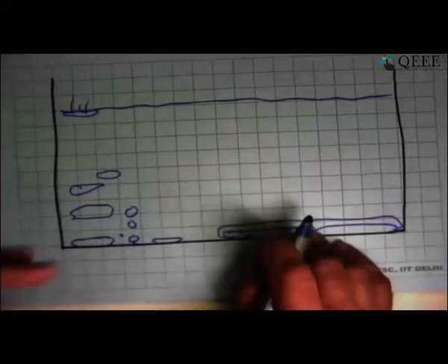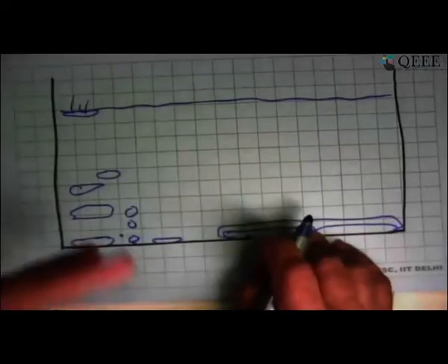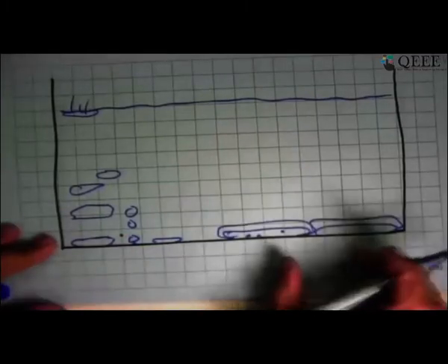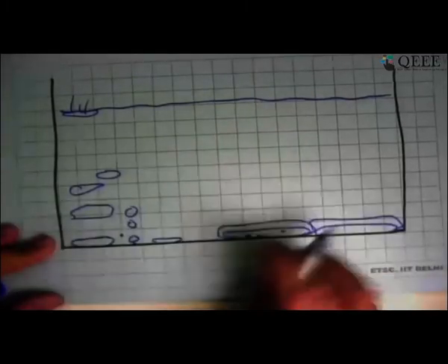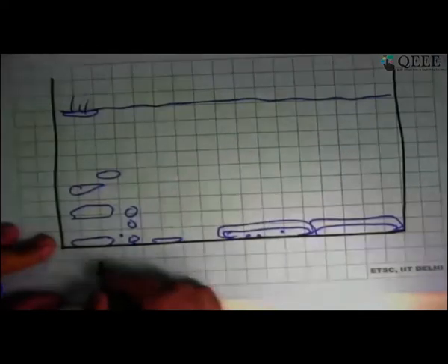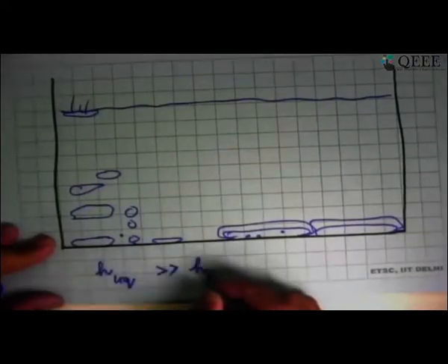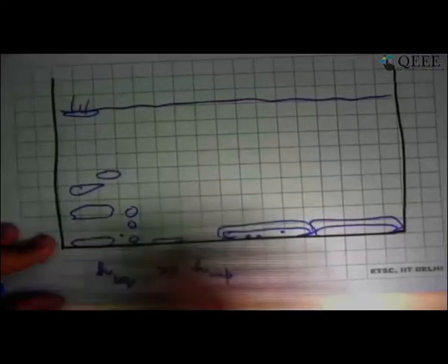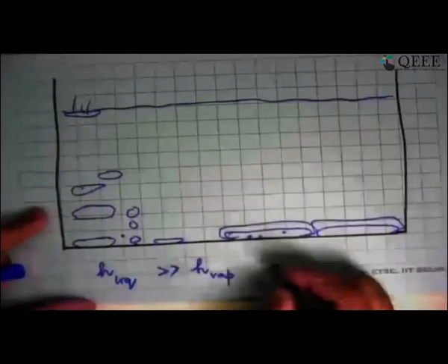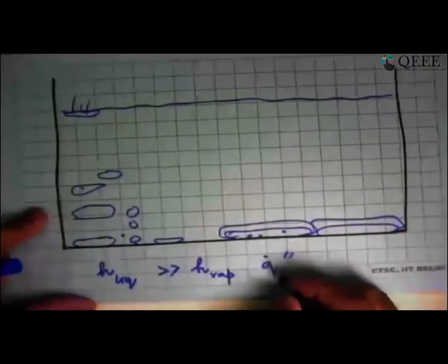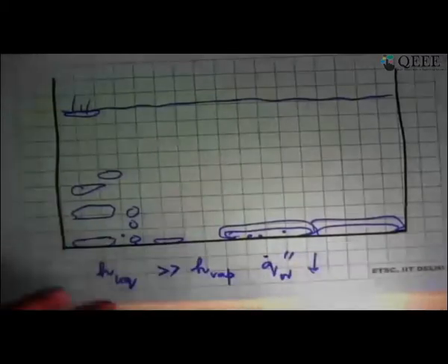Here that is being hugely impeded by the formation of the film, and that's the reason heat transfer coefficient has gone down, because H in general with a liquid is much greater than H with a vapor. And that is what is the reason here. More and more of the surface is seeing vapor blanketing, heat transfer coefficients are going down, and in this case we are also seeing Q dot double prime at the wall is going down.